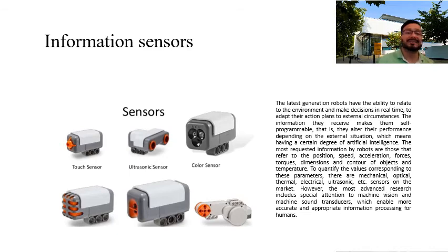External sensors are external to the robot and are used to coordinate the operation of the robot with other equipment in the cell of the flexible manufacturing system. In many cases, the external sensors are relatively simple devices such as limit switches that determine whether a part has been positioned properly in a fixture or that a part is ready to be picked up at the conveyor.